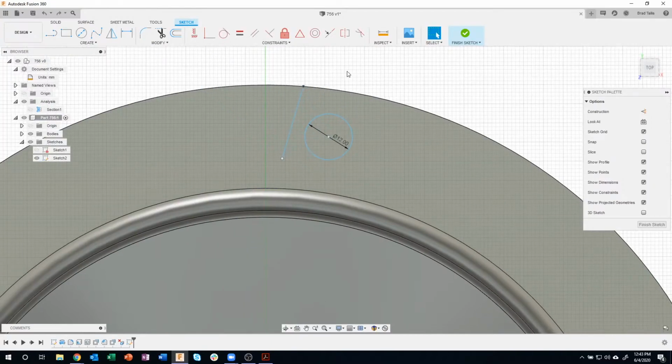Here's my trick. Some people ask, do I use coincident? Do I use collinear? What do I use here? Just grab the point and drag it to that edge, and you'll notice a little X appear, though it's kind of hard to see. I'm grabbing the point in space and dropping it onto that edge, and Fusion figured out to make a coincident constraint.